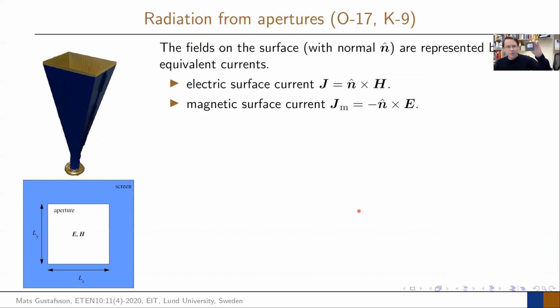When you looked at your patch antenna, instead we said that we had some equivalent currents here and equivalent currents here, and it looked like the radiation is coming mainly from one magnetic dipole there and a magnetic dipole there. And for a magnetic dipole, we have to basically turn the polarization, or say that the magnetic field is dominantly parallel to this magnetic dipole.